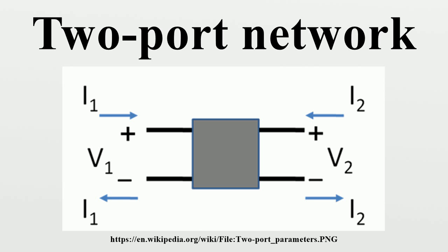The analysis of passive two-port networks is an outgrowth of reciprocity theorems first derived by Lorentz. In two-port mathematical models, the network is described by a 2x2 square matrix of complex numbers. The common models that are used are referred to as Z parameters, Y parameters, H parameters, G parameters, and ABCD parameters, each described individually below.